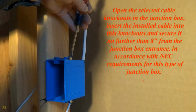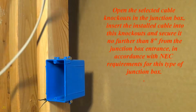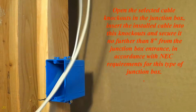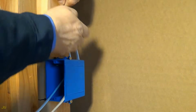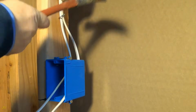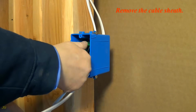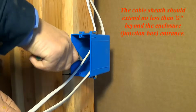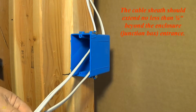Open the selected cable knockouts in the junction box. Insert the installed cable into the knockouts and secure it no further than 8 inches from the junction box entrance, in accordance with NEC requirements for this type of junction box. Remove the cable sheath. The cable sheath should extend no less than 1/4 inch beyond the enclosure, junction box entrance.